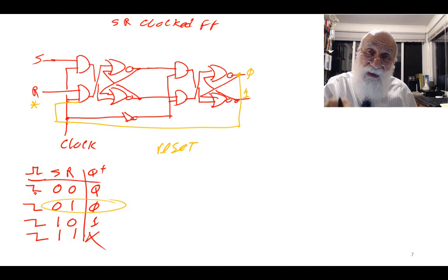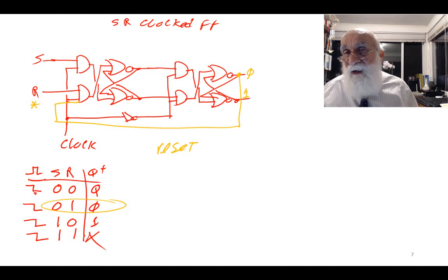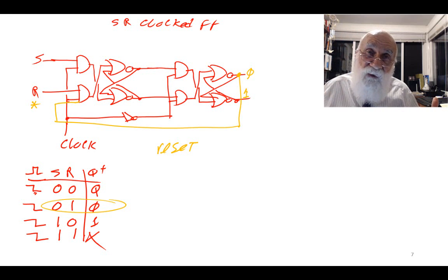What I did, I took that 0 on the outside and masked this AND gate. Remember, this is an AND gate, which means that if one of the inputs is 0, it doesn't allow other inputs to propagate. But that doesn't cause me a problem because even if reset propagates, it's not going to change anything anyway. So I had done no harm by this orange feedback line.